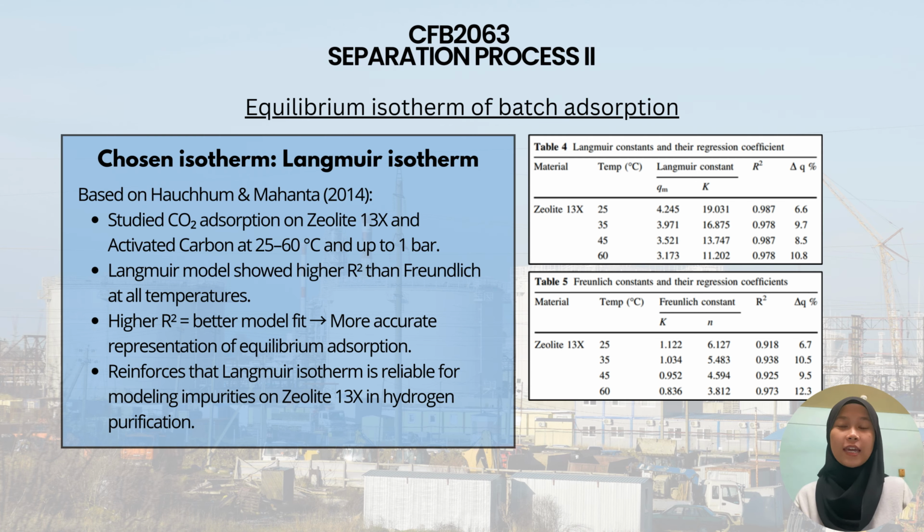Hi, I'm Nurish, and now let's move to the equilibrium isotherm of batch adsorption. Our chosen isotherm is the Langmuir isotherm, based on the literature where CO2 adsorption was studied on zeolite 13X and activated carbon across 25 to 60 degrees Celsius and pressures up to 1 bar. Their results show that the Langmuir isotherm consistently achieved a higher R-squared value compared to the Freundlich, which indicates a better fit to experimental data, meaning that the Langmuir isotherm describes the adsorption behavior more accurately.